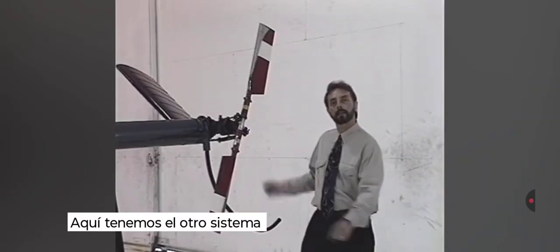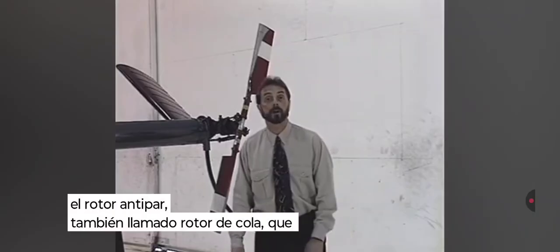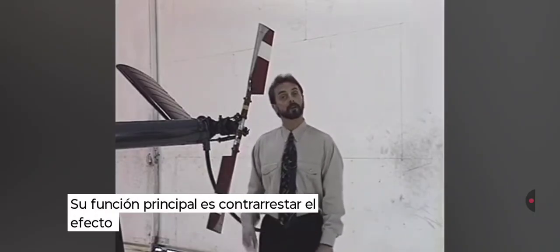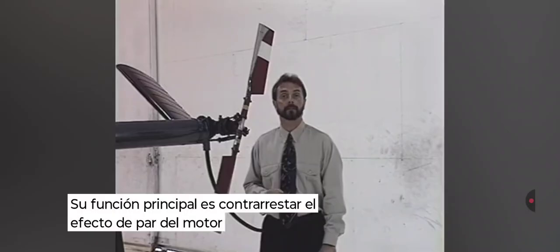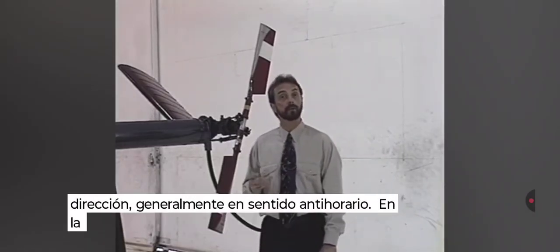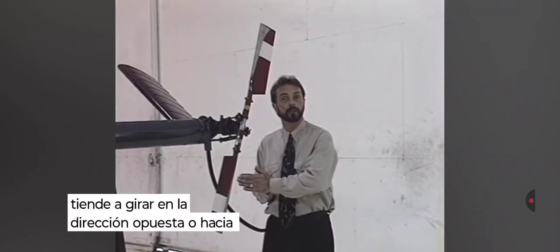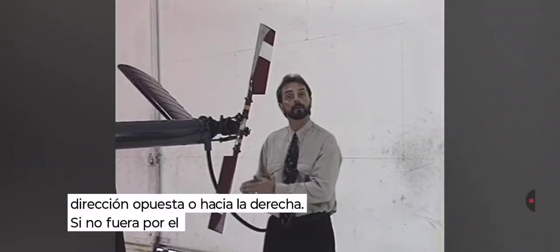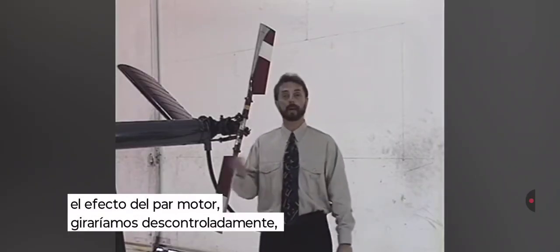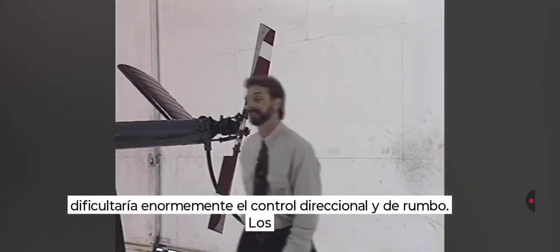Over here, we have the other rotor system, the anti-torque rotor system. The tail rotor, as it's also called, is located on the end of the tail boom. Its primary purpose is to counteract the torque effect of the engine. As the main rotor blades turn in one direction, typically counterclockwise in most American helicopters, the fuselage has a tendency to want to turn in the opposite direction, or to the right. If not for the tail rotor counteracting the torque effect, we'd find ourselves spinning wildly around and around. This would make directional and heading control difficult, to say the least.